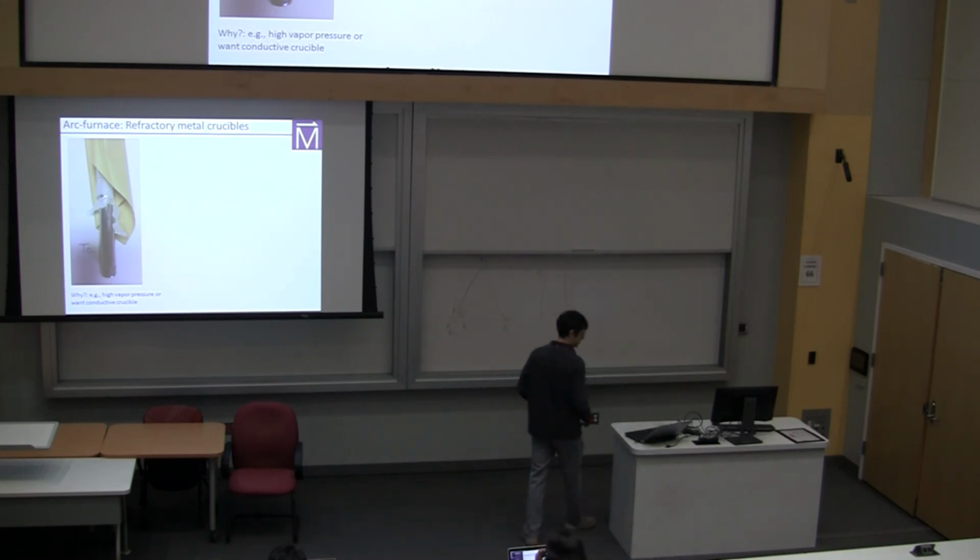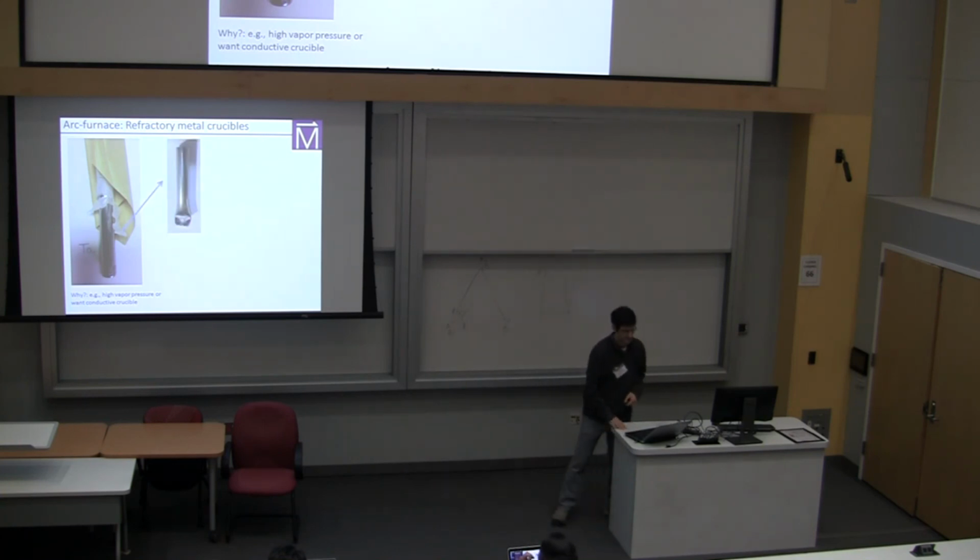Okay, but that's not all. So what you want to do is take one of these tubes, cut off a piece using just a regular pipe cutter, and then here's the most important thing. Now you need to close the end. It's insufficient to just press the end closed and then try to weld it shut. And the reason for that is, again, this wetting property of tantalum. If you press it and then bring an arc across the end of it, it'll kind of pull back from itself, right? And it'll leave holes in the bottom of the tube.